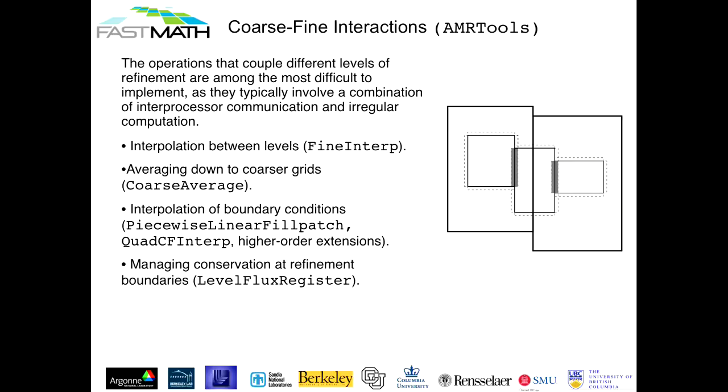And at the end of the time when it's time to synchronize, the very first thing that happens is the coarse grid decrements the register, and then the fine grid increments the register. So at the end of the last step of your finest time step, you have the difference. You know how much the flux was altered by all these operations. Now, how you get that flux corrected across all the levels can either be an explicit operation, you just change the value on the coarse grid for the flux, or you might need to do a solve. It depends on how stiff that particular PDE is.